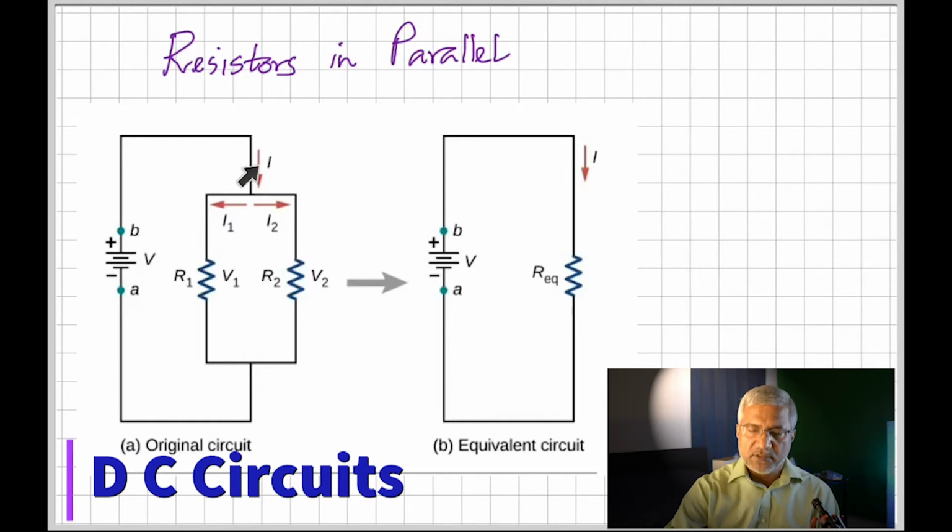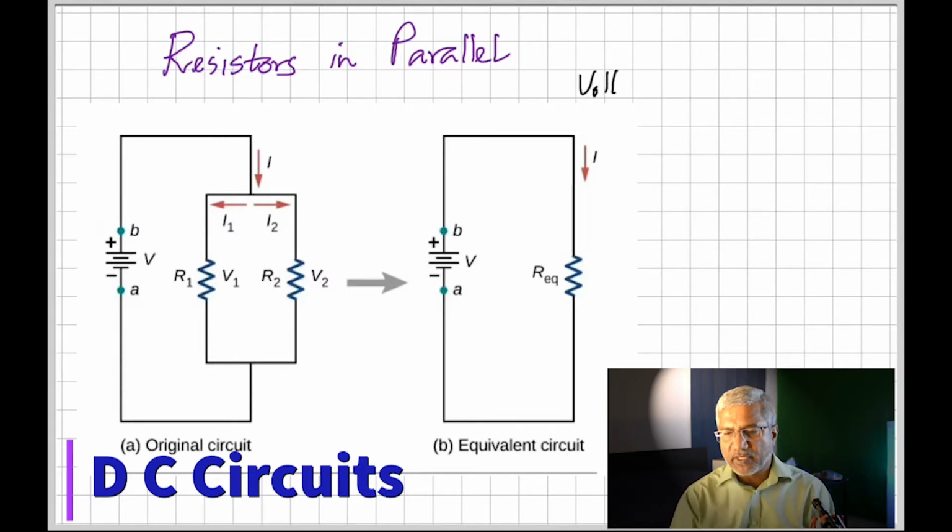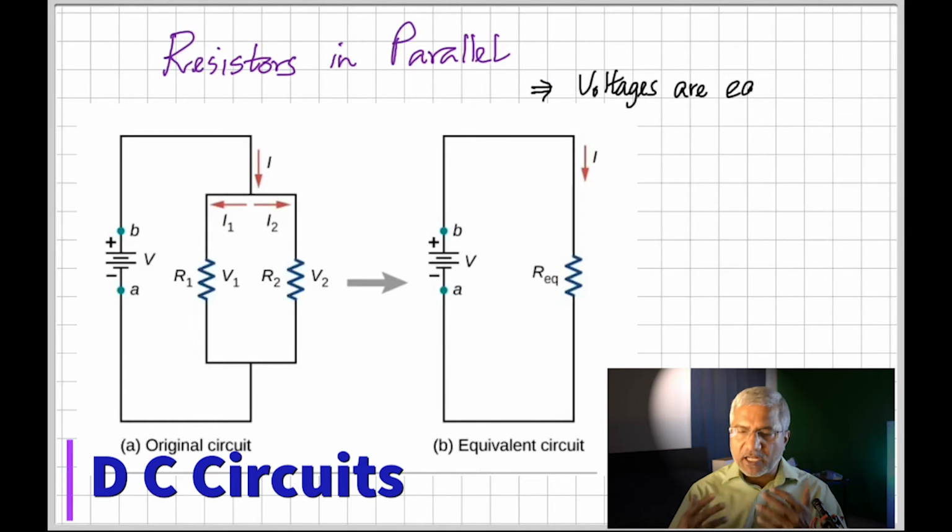Yes. So if you had three resistors, that would be the same thing. When you add, I should be equal to I1 plus I2 plus I3. So the currents always add up. So I'm going to write that. The voltages in parallel are equal, the currents are different, and when you add all the currents, you must get the total current. That's the basic idea.